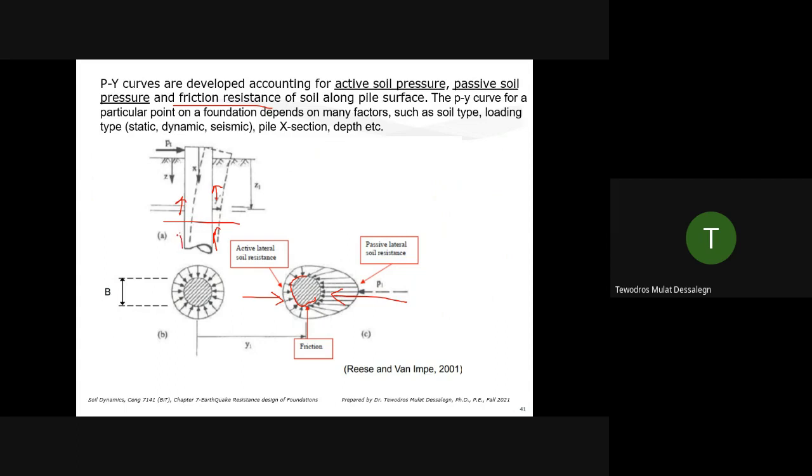Let's say you have a good soil that doesn't liquefy. So that's what LPile is doing. It's doing all these steps at every depth, and you provide PY curves so it can develop the springs and analyze the entire thing. Is it doable by hand? It would be too complicated. It's really solving that fourth degree differential equation. So that's why we need the software.